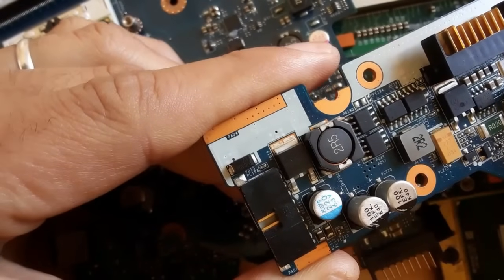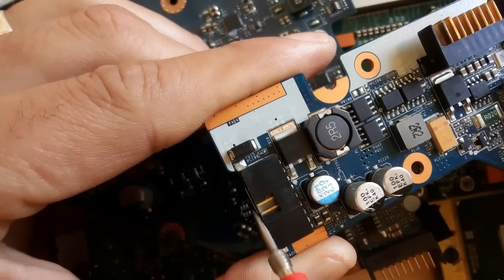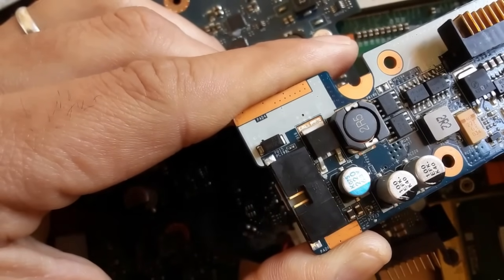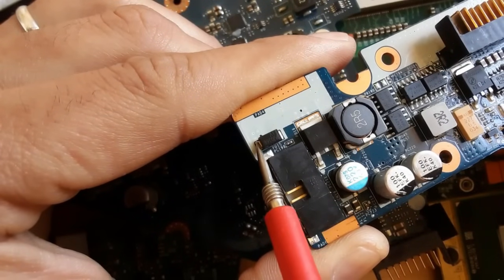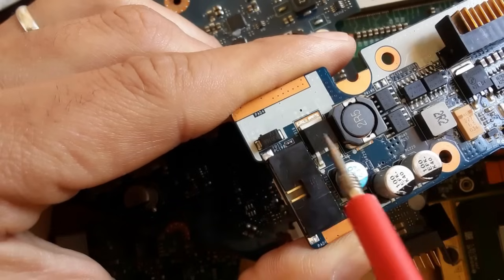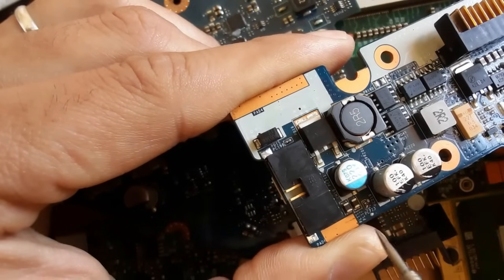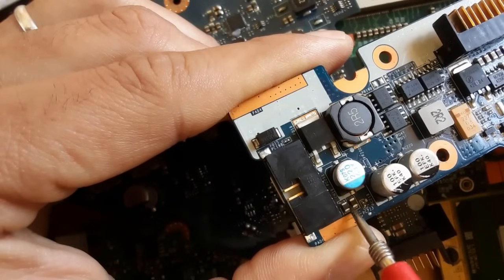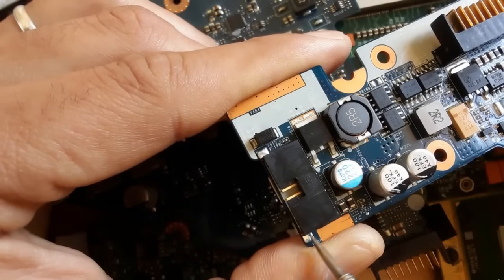Here this is the power connector, and near the power connector we have the diode. The diode is for protection. When there's a problem in the voltage or current, the diode will be shorted to the ground and then protect the other components and other circuits. Here we have two coils. Usually you will find coils near the power connectors and the diode, of course. Sometimes you can find the fuse, etc.